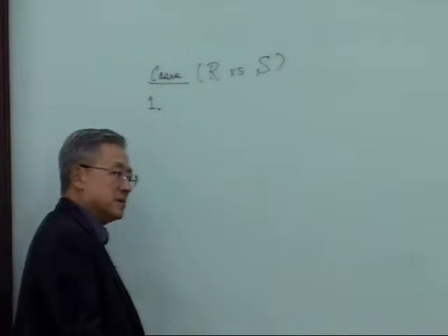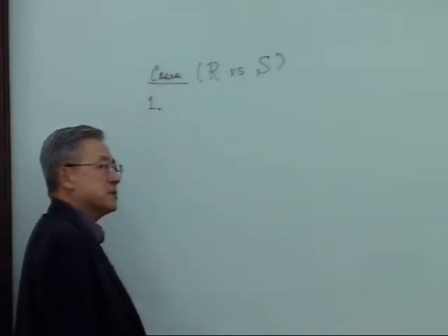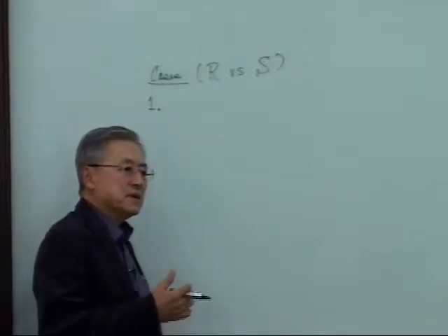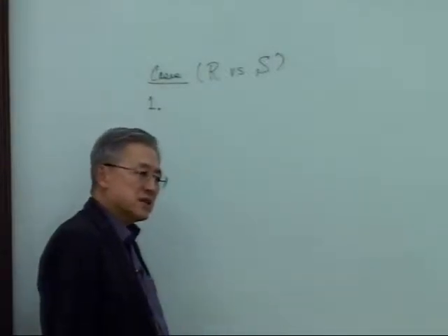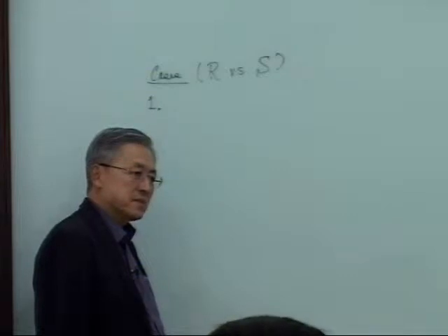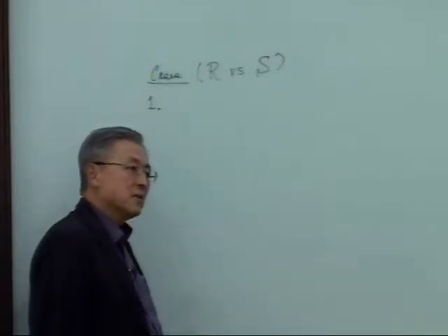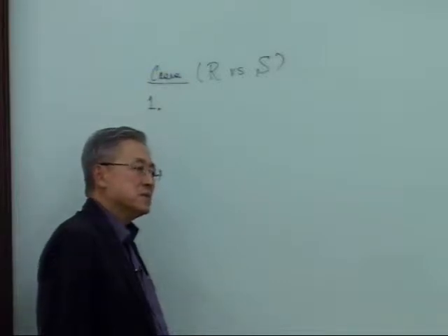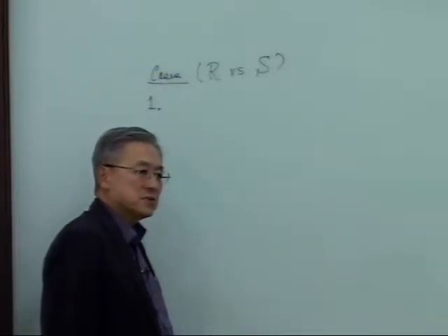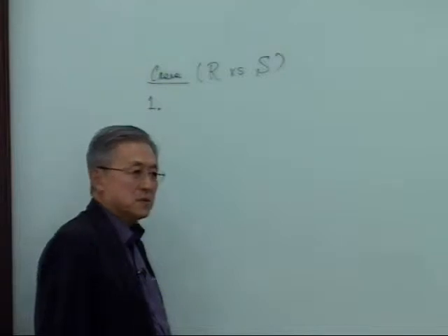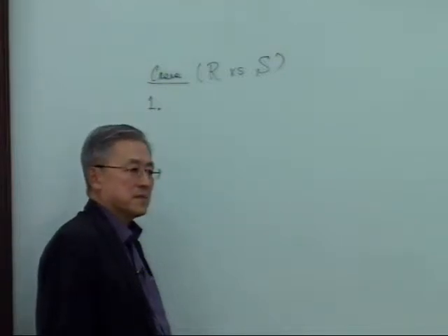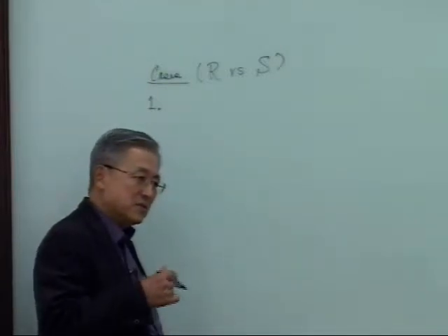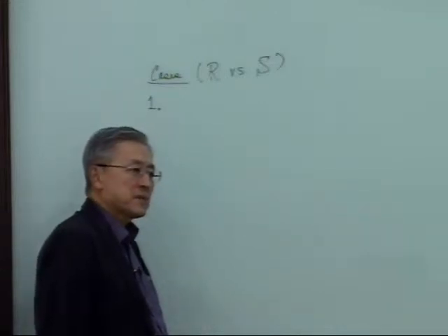So how does the safety factor, or factor of safety concept, apply in the design process? I'm insisting you multiply the safety factor by the actual stresses or actual loading, not reduce the resisting strength.